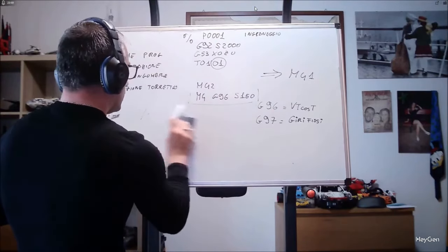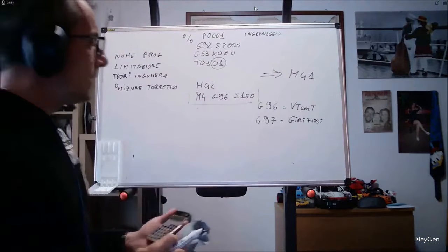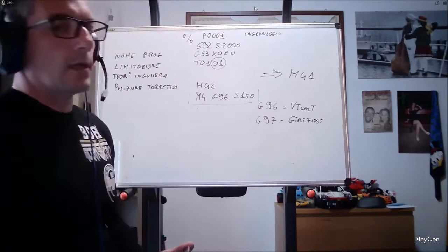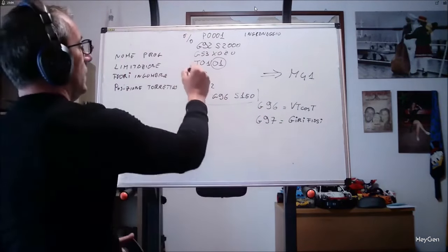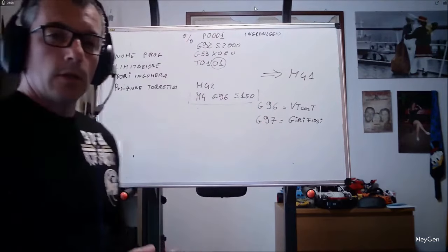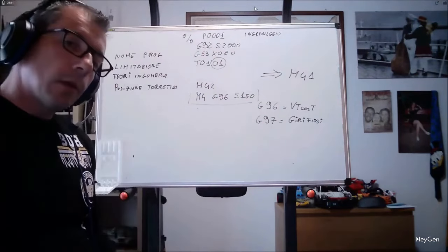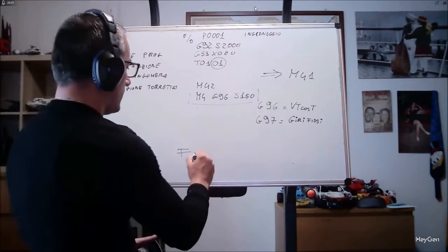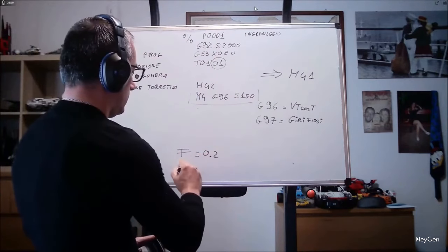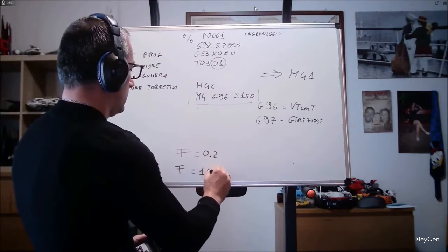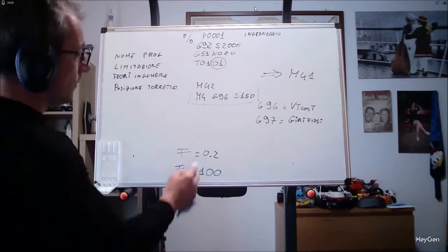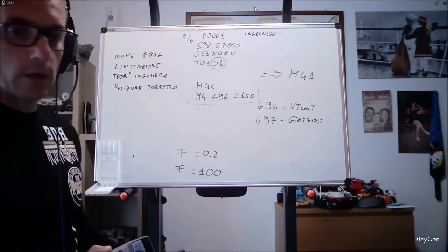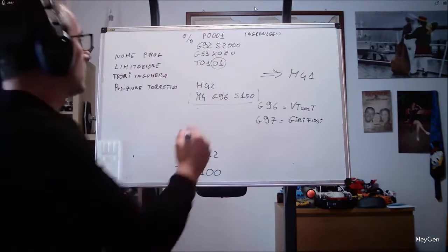Just as we can adjust the way the spindle rotates, that is in fixed RPM or constant cutting speed, we can adjust it. And we must input it initially, the way the machine reads a feed rate. Later I will teach you that through the F function we will input the feed rates. You will almost always find wording of this type in your turning programs. In milling you will find very large numbers. Here we need to input.